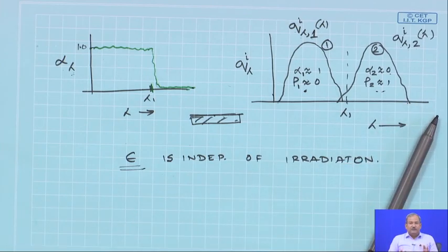Therefore, there is no basis to say that alpha is always going to be equal to epsilon. So, hemispherical absorptivity and hemispherical emissivity may not be equal. We have to be careful while using the relation emissivity equal to absorptivity, to know what the irradiation field is. It has to be mentioned that the surfaces we are talking about are gray, so they do not have any directional or spectral dependence of the properties.